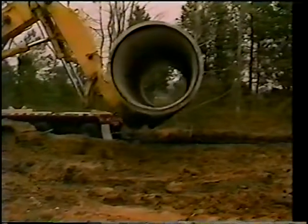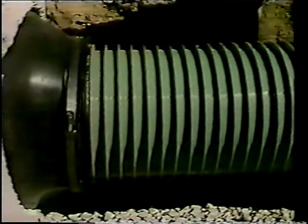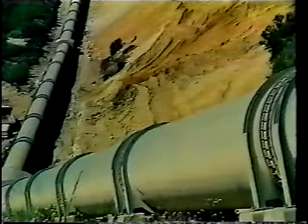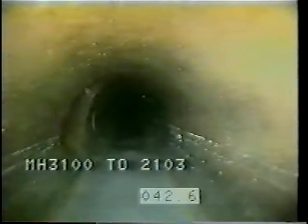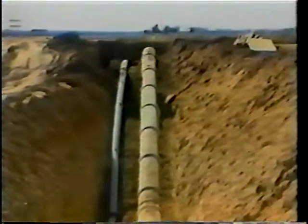First, we must distinguish between pressure pipe and non-pressure pipe. This pipe carries treated water. It is kept full and under pressure. A sanitary sewer or storm drain, on the other hand, is not usually pressurized and is seldom full. We also distinguish between types of pipe according to the way they interact with the surrounding soil, between rigid and flexible pipe.